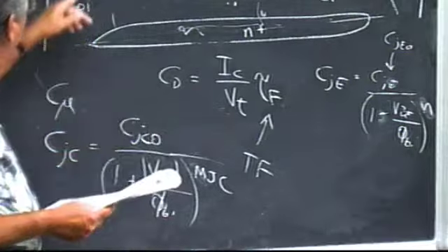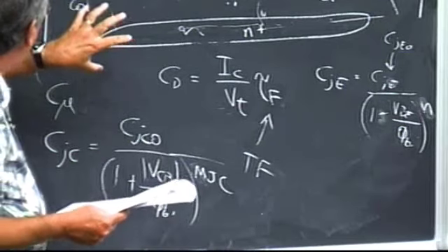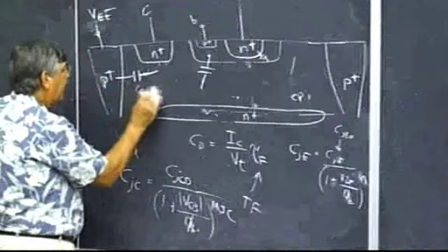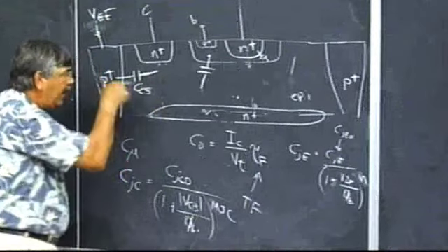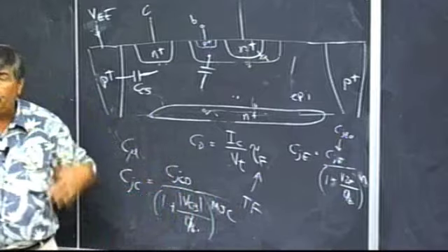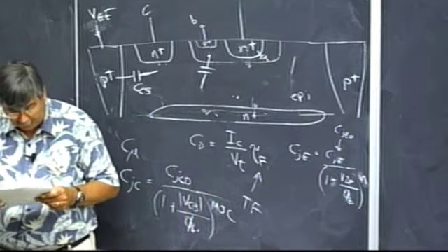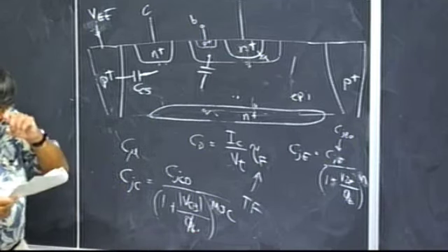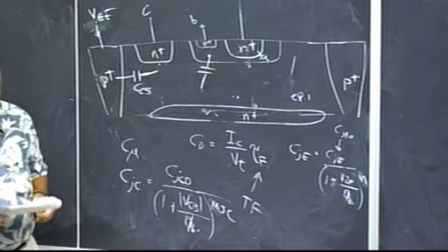There's also a capacitance from the substrate, so there's a collector to substrate capacitance, CCS. It's a junction capacitance. It's got an area. It's got one of these kinds of dependencies, etc. So there's a lot of repetition here. There's more details, but that's a pretty good bit, and that's probably about all we're going to have time for.